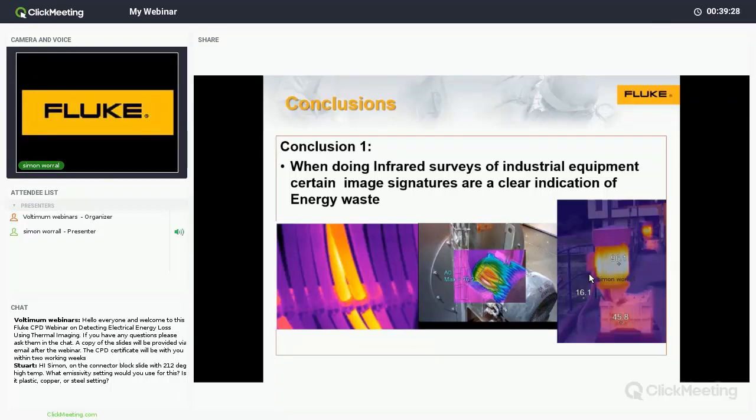On the middle image and the right-hand image, we've got overheating motors. That can be from a number of causes. The overheating could be simply a terminal connection problem, so we've got heating at our terminals that's been transferred into the motor. But more likely, it will be from a breakdown in the insulation resistance or the insulation of our cabling, which generates heat before it actually fails.